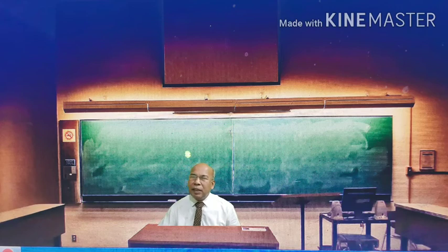In twinning, a mirror image is there. In slip, a mirror image is not there. In slip, one part of the body moves over the other part and therefore a crack may occur. But a twin takes place internally, so a crack may not occur. Slip occurs due to the shear component. Twin occurs due to a suddenly applied load or impact load. It may also occur due to annealing, heating and cooling at slow rates. So in these ways it can be compared.